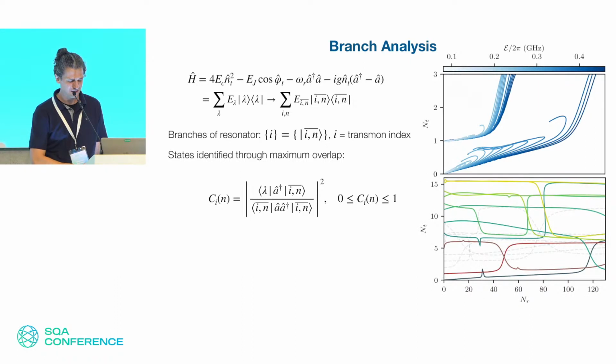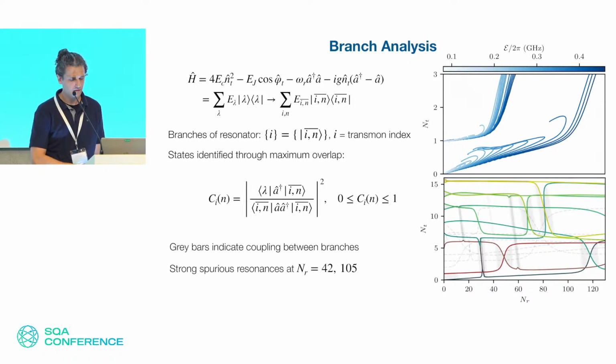So I'm just going to make a point here that these ionization thresholds are associated with instabilities in the spectrum of the system. We have a way to track all the states in the spectrum. And we note that there are certain resonances between the low-lying states in the spectrum and other states above, between, say, 5 and 7. And these states give us the possibility to tunnel outside of the transmon well. And essentially, we can immediately trace, in the semi-classical analysis that we do based on the undriven spectrum, the positions of these instabilities, and we can understand the threshold of ionization.